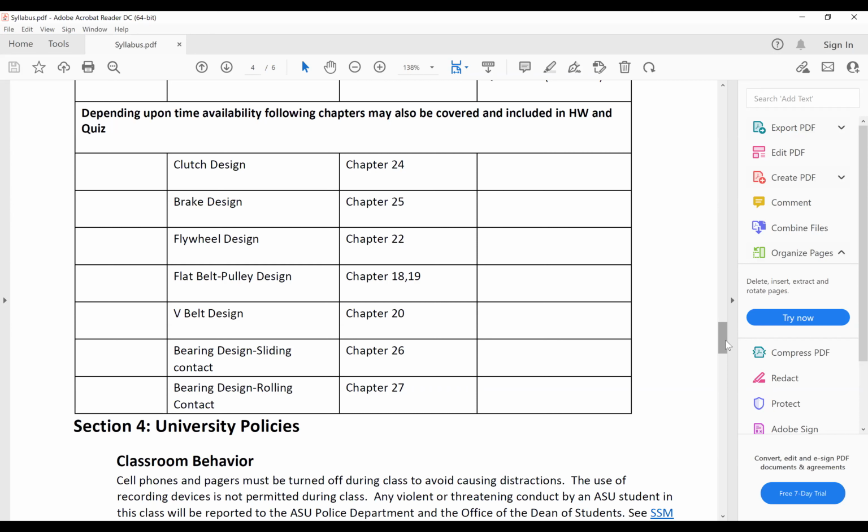some random object. Say, how do you design this bottle? And then the same design principle. So this is like a pressure vessel. The only thing is there is no pressure inside, but you will check for hoop stresses, transverse stresses, the failure, then you'll see for the internal pressure limits and all that stuff. Or how would you design this lever? Once you know what is the finger force that an average human can press, is about anywhere between 10 to 50 newtons, then you can actually design the lever arm and all that stuff. So that will be discussed in this class.